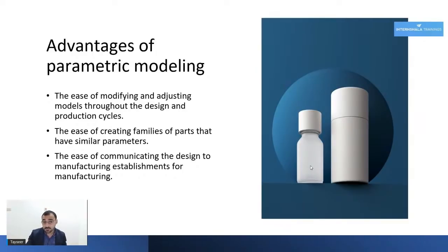A cup was a very simple example. Engines have the same thing. Engines often have different sizes. Pistons have different sizes. PS5 has different sizes as well. And so all those types of designs, we can call them families of designs, we can easily make with parametric modeling because we're only shifting selected parameters while keeping the rest of the design intent.